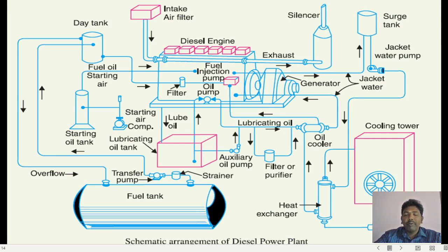If you're going for a hydroelectric power plant, the water will be readily available. But in case of a diesel power plant, you should have a required storage. That is what is shown here. See, this is the fuel tank. It is like a storage of fuel at a particular place. You will be taking the fuel from this fuel tank. It is called a day tank, where you can monitor the day-wise release of the fuel. So this entire portion is your fuel system. Fuel is taken from this tank and given to your diesel engine, and there the diesel engine will be working and producing your mechanical output.